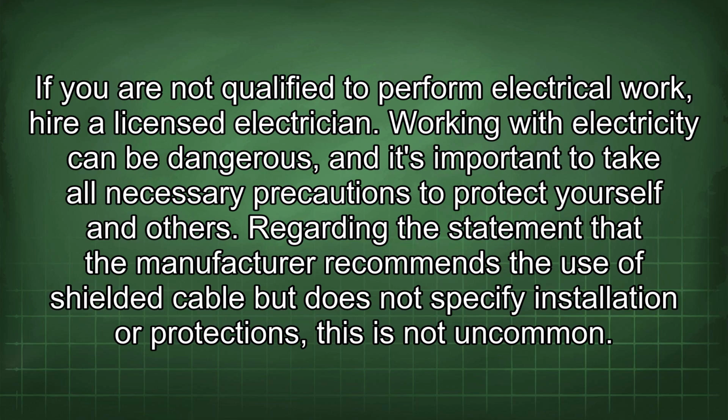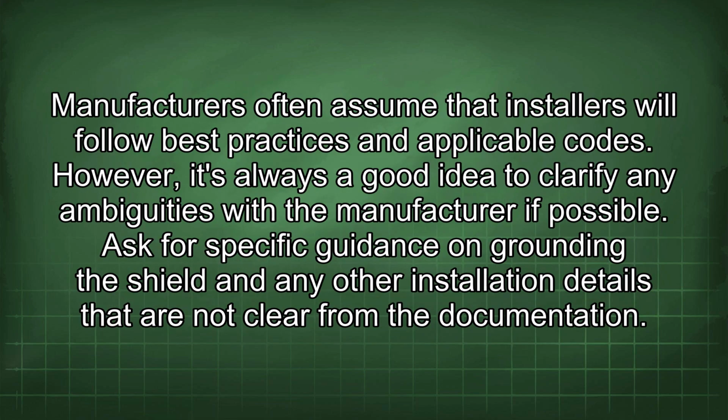Regarding the statement that the manufacturer recommends the use of shielded cable but does not specify installation or protections, this is not uncommon. Manufacturers often assume that installers will follow best practices and applicable codes. However, it's always a good idea to clarify any ambiguities with the manufacturer if possible. Ask for specific guidance on grounding the shield and any other installation details that are not clear from the documentation.